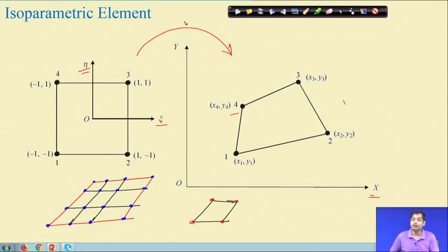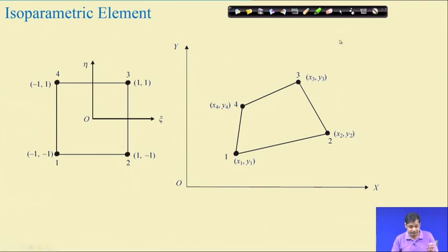Okay. So, this is called isoparametric formulation. Why is it called isoparametric? Let us not bother about that right now; we will come to this point shortly. Now, this is the isoparametric formulation, or the concept. There exists a formulation through which, even if your elements are not perfectly square or perfectly rectangular, you can map this to an element in a parametric space, do all the exercise, and get the final approximation, the final stiffness matrix of this element. Okay. This kind of formulation also exists and is very common.